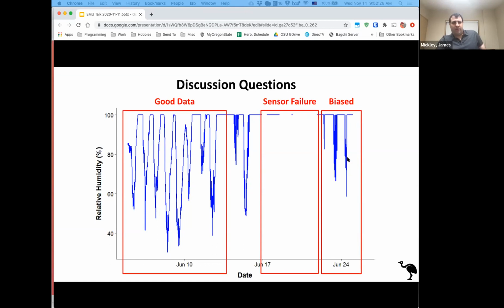And so why is this? Well, every humidity sensor I've ever seen has to be open to the outside air to do the sensing. So they all have a tiny hole. In some cases, you can put a membrane over that hole to try and protect it, but every single humidity sensor has to be open to the outside air to do a good job. So we have this trade-off between waterproofing versus accuracy.